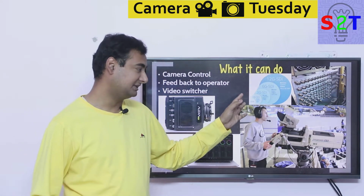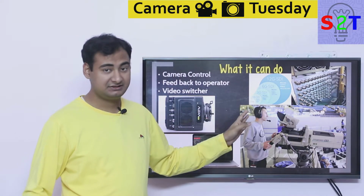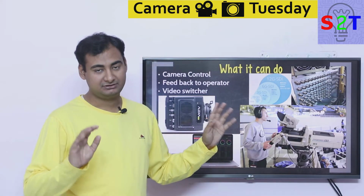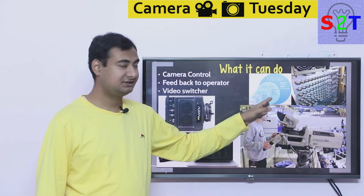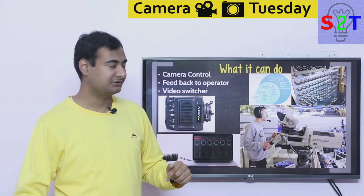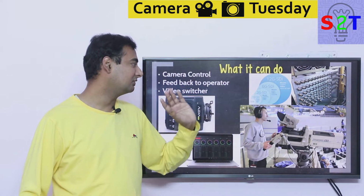So you have basically old SDI, which used to be used in very old days. Then we have HD-SDI. Then, if you want good quality video, you must go to 3G. 3G simply specifies how many gigabits per second, small b. Then you have 6G. If you want 4K 30 frames per second, you must have 6G. Now if you want 4K 60 frames per second, you must have 12G. Now 12G is a bit rare as of now, not every camera has that.